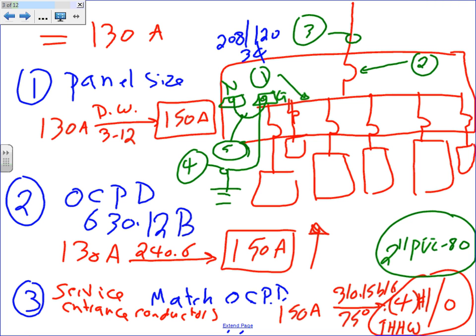Remember what we did yesterday? You take the volt-amps for all the lights and multiply them by 1.25. All the receptacles in that welder shop, the convenience receptacles, you derate them if they're more than 10K. Add them all up, and at the end you change them into amps based on the voltage and add them to this number, because you can't add apples to oranges, right?